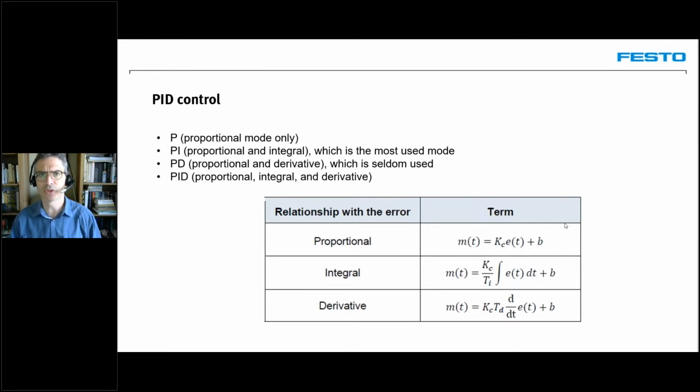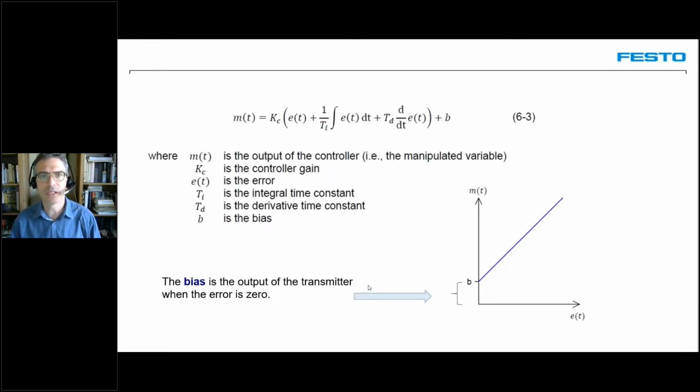So this is the proportional term. The integral term is where we will correct long-standing errors, but I'll discuss it later. Finally, the derivative parameter takes the variation speed of the error. So at what speed does the error change? We will add a term responding to the speed of change of the error, which will yield the derivative parameter. But we'll come back to it in a moment.